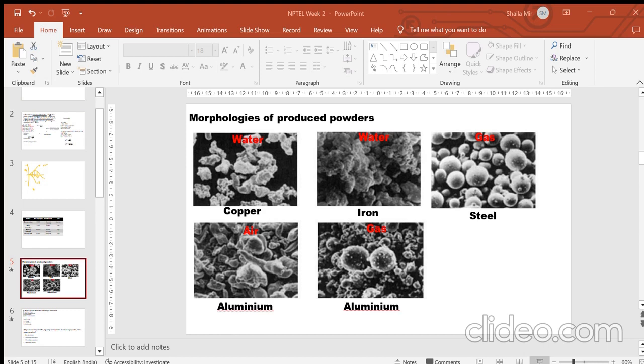Right, because we are talking about an embryo in the nucleation. So we are saying what is the starting particle of the nucleation and the growth. It will not be a stable particle below the critical radius, because critical radius is the requirement for nucleation to take place. We saw in that diagram that if the radius is less than the critical radius, then it will shrink and completely vanish out. So it will not be stable. That statement is wrong. The right option is the unstable particle which is below the critical radius.